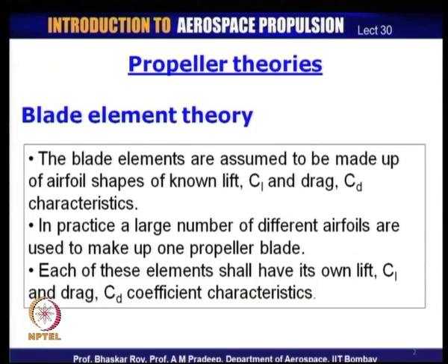And each of these elements have their CL, CD characteristics, and in addition they have, as I just mentioned, their incidence range, which is built into the shape of the propeller that is being deployed over here.